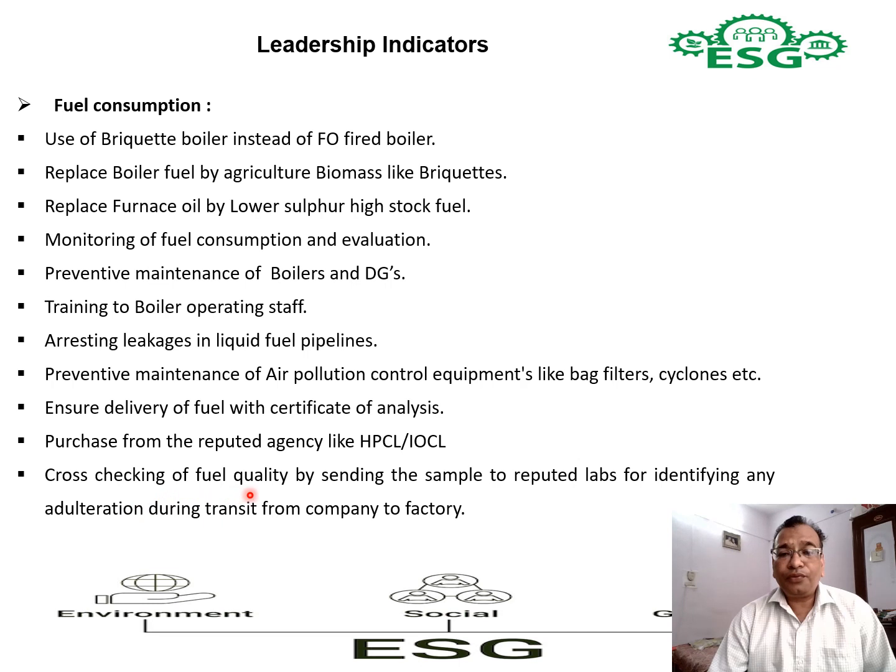Then you have to cross check the fuel quality by sending a sample to a reputed lab for identifying any adulteration during the transit from the company to the factory. Now this adulteration racket is increasing. We just cannot believe the face value of the COA of the company, because the COA is based on sampling at source. But when the vehicle travels many kilometers from the source until it reaches the final destination, you never know. There are seals and many interlocks, but people are very clever. Wherever they get an opportunity, they break the seals and adulterate the fuel.